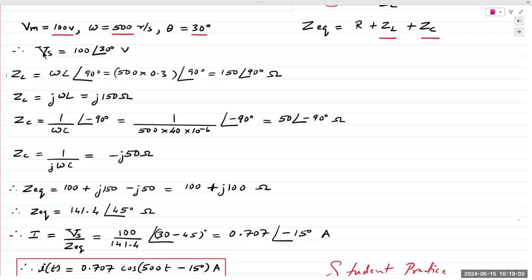So if I have to perform addition, subtraction, multiplication, or division, I need the values in both polar and rectangular coordinates. And again, as engineers, you should be aware of how to solve this. This is an approach where you can solve this with any calculator. You do not need a highly specialized programmable calculator. And that's why you see me finding the values for ZL and ZC twice.